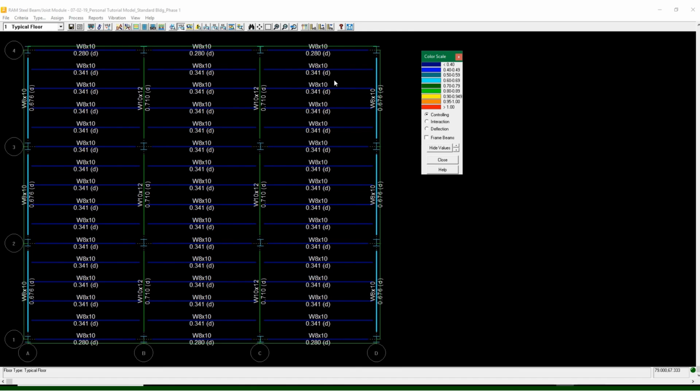So that ends up controlling. Like I said, oftentimes that's the case. But we can see that on the perimeter, we have the stress based on deflection, if you will, allowable deflection. And we have about 70% of the capacity being used. Here, 71% of the capacity being used. Here on the perimeter, we expect this one right here to be the same as this one. It is. It actually would be the same as any one of these. They're the same tributary area, same length, all things being equal. All these right here on the interior will be the same. On the perimeter, it's different.